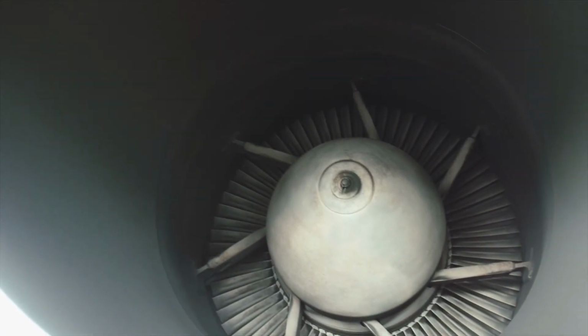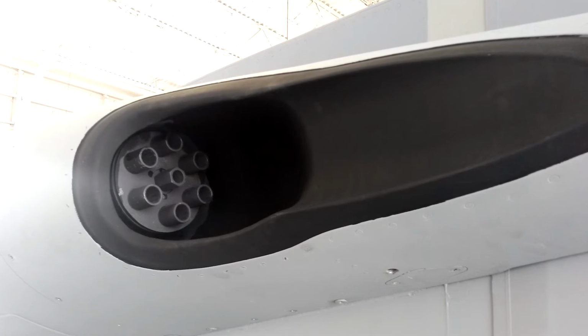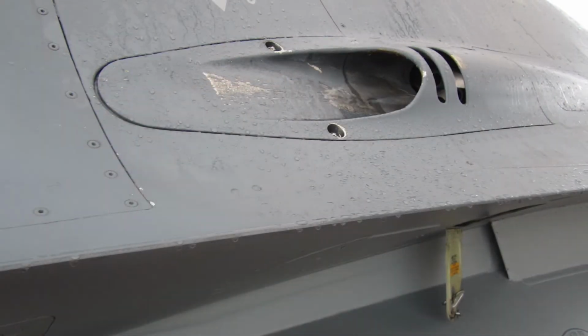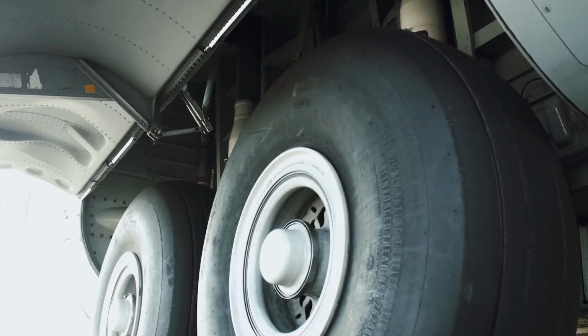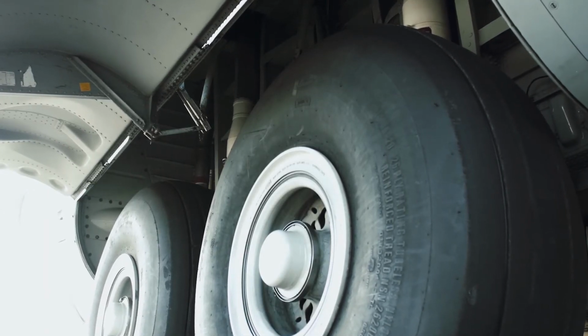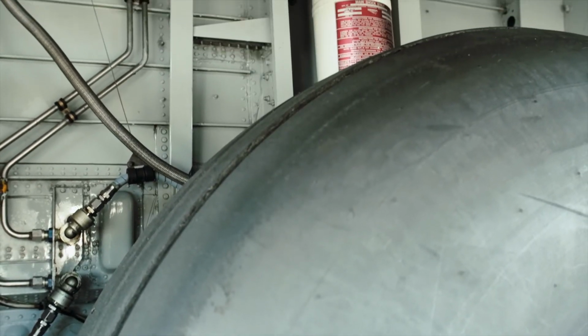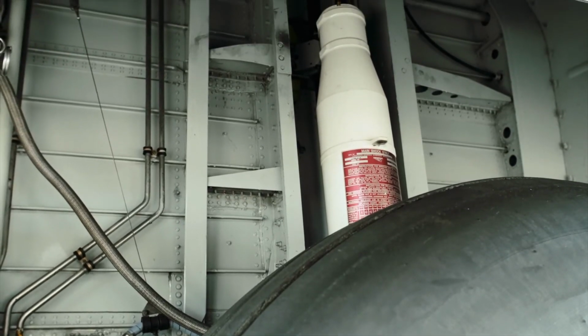Engine exhaust areas are often blistered by heat. Gun and missile exhaust surfaces are also blasted away by high-velocity gases and shell casings, causing damage to the protective finish. In addition, these areas can become potential water traps. Wheel wells and landing gear assemblies are extremely susceptible to corrosion because of exposure to the environment. These areas are also vulnerable to water entrapment.